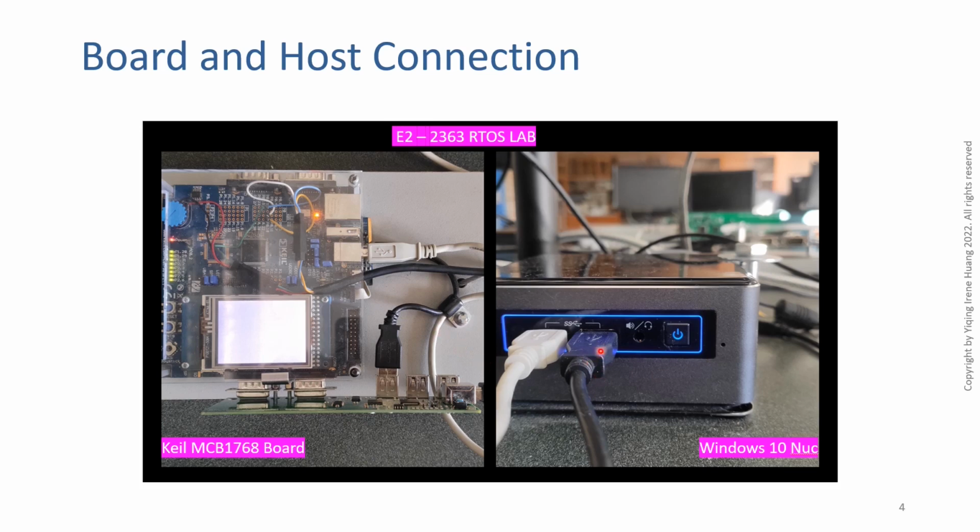Then there's this USB cable that connects to the end of this green board, which is an adapter that allows us to access the serial ports on this microcontroller through the USB from the host computer. And you can see there's another USB cable that connects to this little board here. See the golden edge here? There's a daughter board underneath this motherboard. This is the mechanism that allows us to download the code from the host computer through USB to the microcontroller.